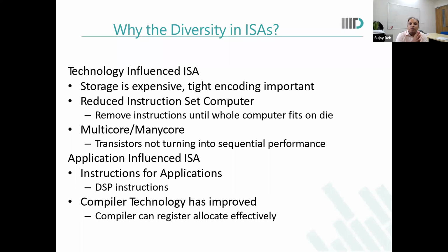And if we identify that, for one instruction, the microarchitecture is becoming very complicated, we'll figure out whether I can live without that instruction. Also, depending on my constraints, I'll find out what all I can put in together, and based on that I will decide what ISA I want. For example, if I want floating point arithmetic, then I know I have to spend a lot of additional hardware and overhead.